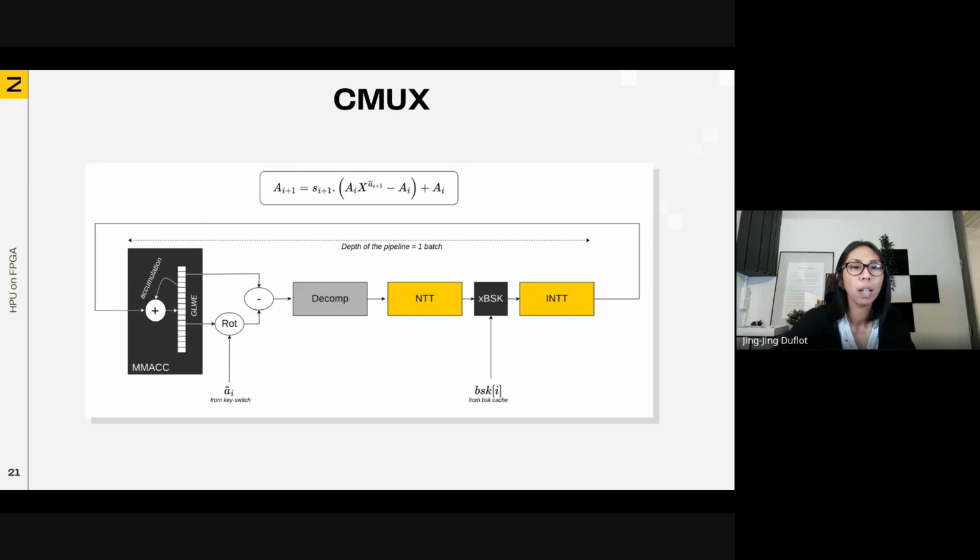On the right here, you will find the RAM that stores the results of each iteration and the accumulation. And concerning the convolution, like everyone else, we are using an NTT to reduce the quantity of multiplications to do. Of course, a multiplier is very costly.